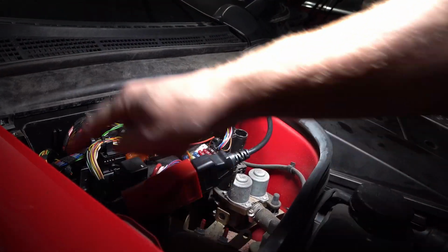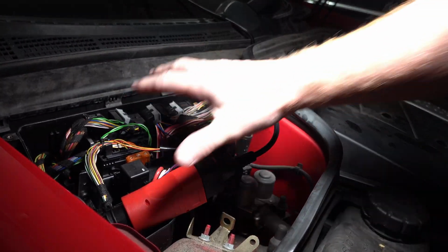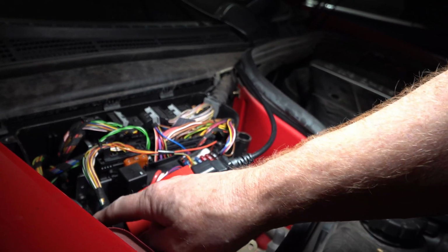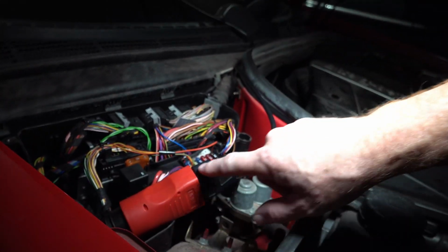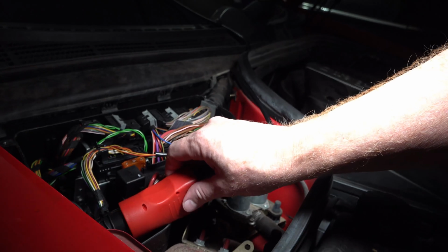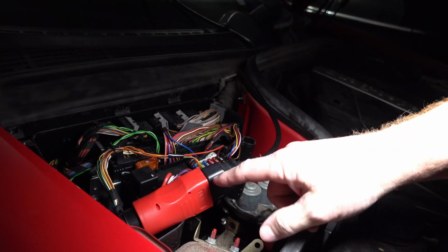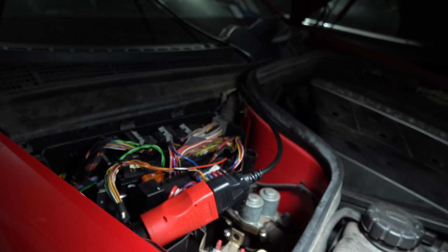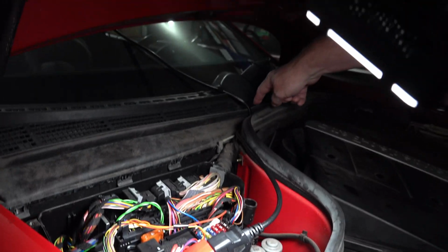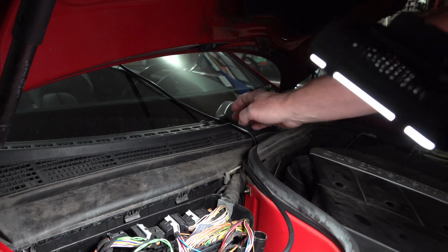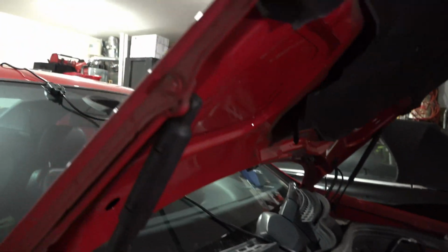I took 4 screws off the top of this box and took it off. Then I took 2 screws off of the connector so I could connect it up at an angle. The reason I did that is otherwise it was standing straight up, and if you closed the hood, you would bend all the wires and maybe break some. So then I took this around this route so that it doesn't get pinched by the hood. Let me close this.